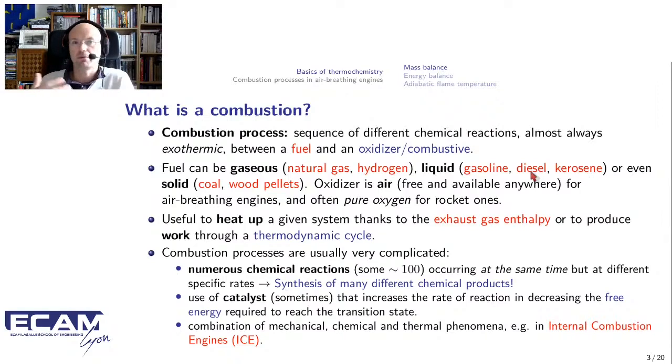There's a lot of trouble that goes with this kind of fuel because it's a gas and it's really complicated to transport a lot of chemical energy in a limited volume, because either you need to increase the pressure to an order of magnitude of 400 to 500, sometimes 700 bars of pressure. So it's really high, and so the reservoirs that are transporting this fuel are really complicated to manage.